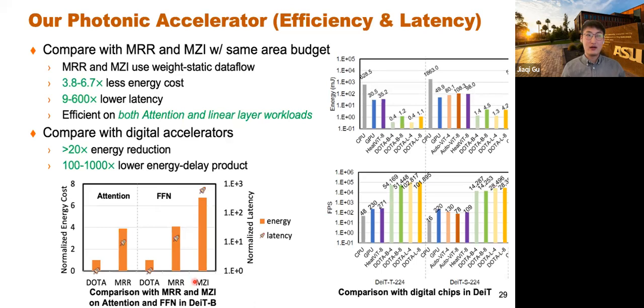Yeah. And instead of just having integrated photonics on chip, we also have free space optics, right? If you have heard about the diffractive optical network, the spatial light passes through some lens where the diffractive material causes interference and diffraction, and the light is received by the camera, they can enable ultra-parallel computing, right? But it's not very programmable. So you combine the programmable integrated photonics on chip and the ultra-parallel free space optics. I think the hybrid way will be the best for optical computing.